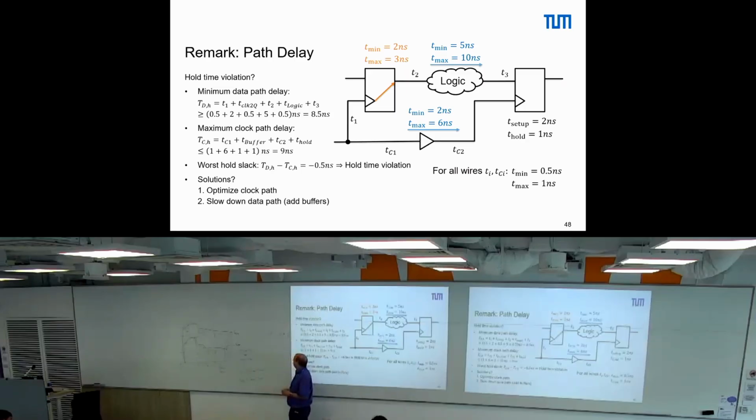So you could theoretically, as you said, also try to increase the hold time. How can this be? Well, you have maybe different flip-flops in your library with different hold times, and you can take another one. Might be. Otherwise, you have to go to your analog mixed signal designer and ask if they can do it. But usually on a digital design level, you just add a buffer there.